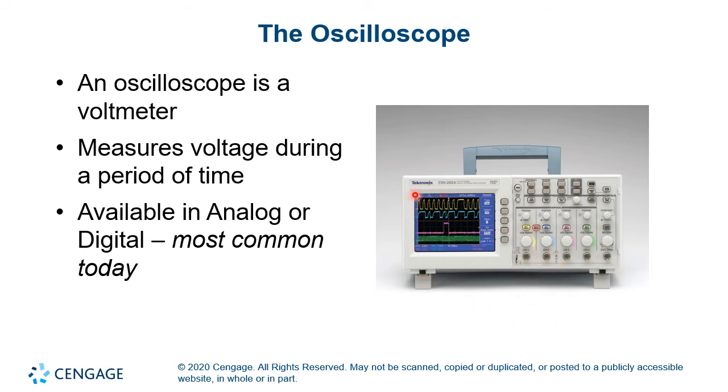Now, all an oscilloscope really is, is a voltmeter, right? It essentially measures voltage. So what you're seeing on the screen is various voltages. Now, why they're not just a value is it's a voltage over time. So what this is showing is how the voltage changes over time. In this case, would be connected in multiple locations, right? This can be done with an old CRT where a trace would actually measure out. That's what the analog devices do. Digital, on the other hand, actually processes it and converts it over to a signal to a digital screen.